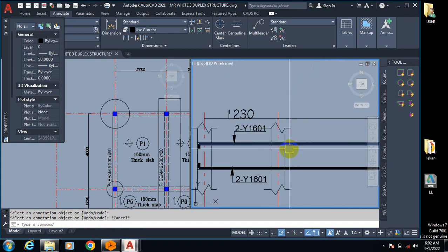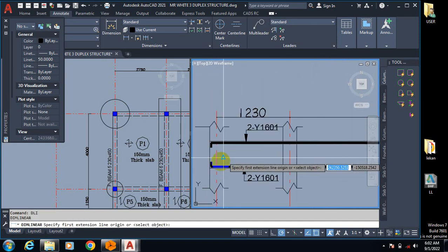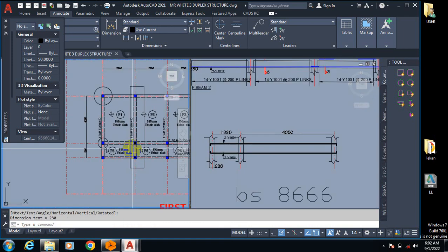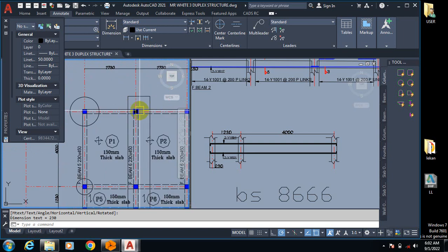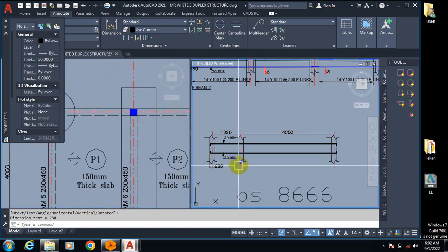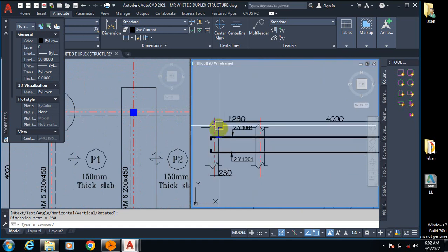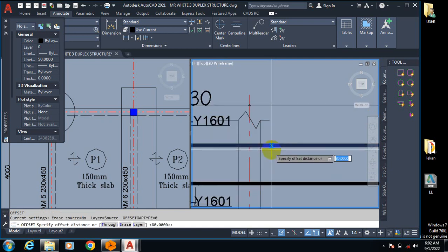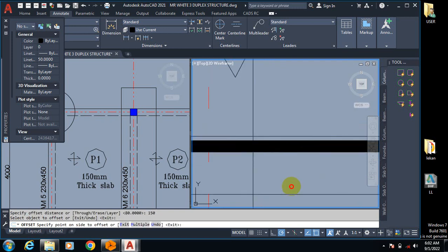And then here you can see where I was able to explain that these are my columns at those supports. We have up to 3 different supports here. If you look at this, we have a support here, a support here, and another support here. So this is 1, 2, 3 exactly. But then we need to capture the slab. Everything is actually cast monolithically together. So if that is correct, the slab thickness for this design is 150 mm, based on what we have gotten from here.